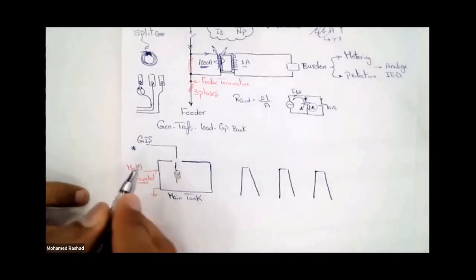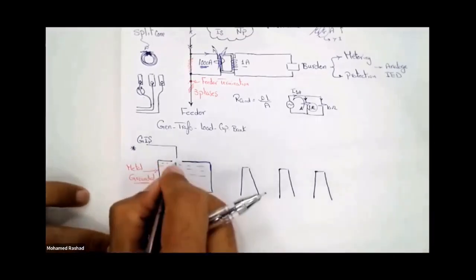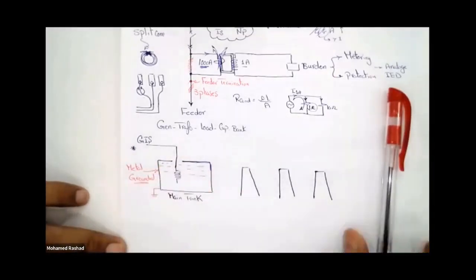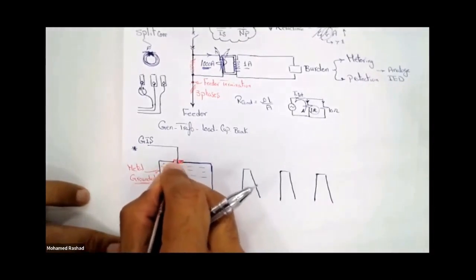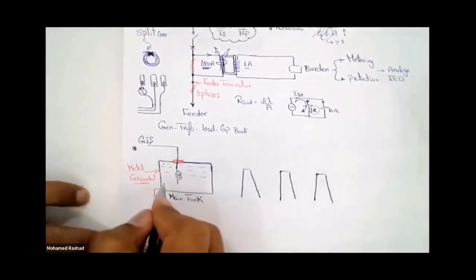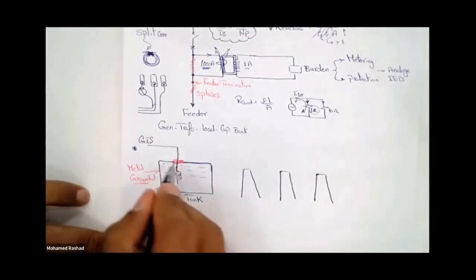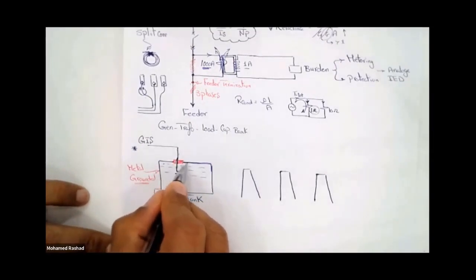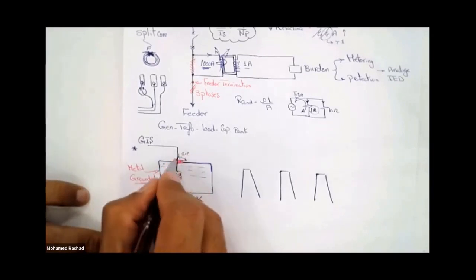If you leave a distance here like this, what happens? You are exposing the oil or opening the tank. So this distance, engineer, to connect these two together, must be sealed. So how do you seal this distance? It can't just be left open, right? The other thing is, I can't just lower my conductor like this, because, as I told you, the insulator between the conductor and the tank body will be air.